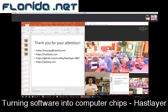Also, if you are using arrays, you have to statically define the size of the arrays as well, because on the hardware you will get a series of registers or something like this, and it's only possible to implement that on hardware if you know how many of them there will be.